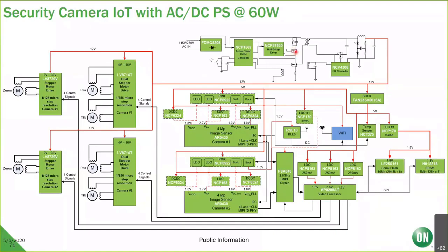So this FET here controls the snubber, which recycles the leakage energy from the primary side. When this FET turns off, it recycles it back into the load. I'll talk about that next week. And then this is a secondary controller, the NCP4306. I'll talk about that Thursday. And this goes down into more power tree of the temp sensors, LDOs, serial flash.